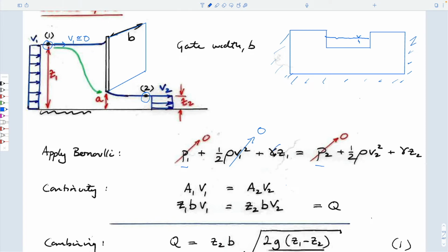They're not at the same elevation. And of course, we can't throw those away this time. In fact, for something that isn't in a pipe with a pressure upstream driving it, it's purely gravity that's driving it. It's the change in potential energy between the upstream and the downstream which is driving it. So it's this term, Z1 and Z2, which is driving it.